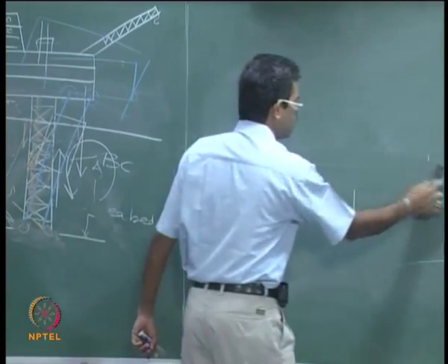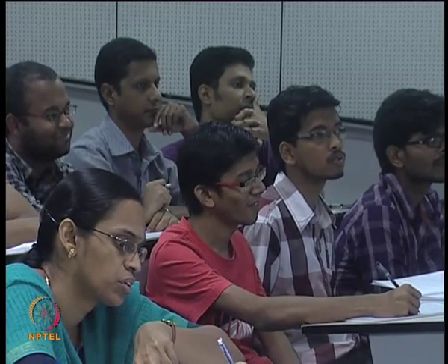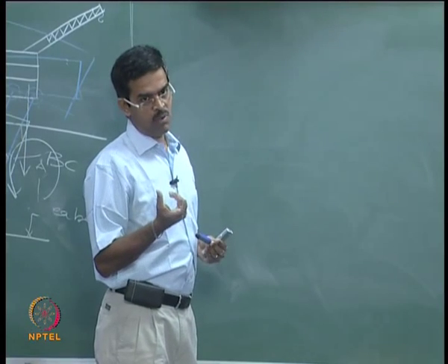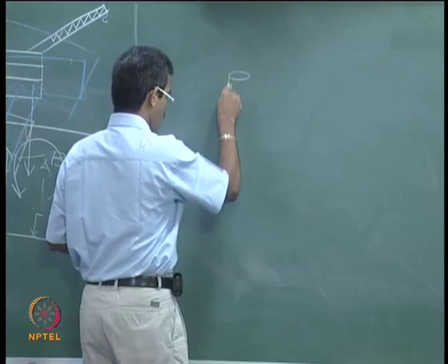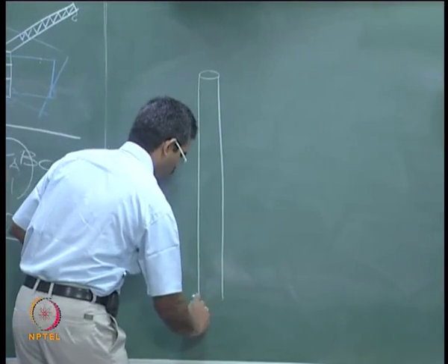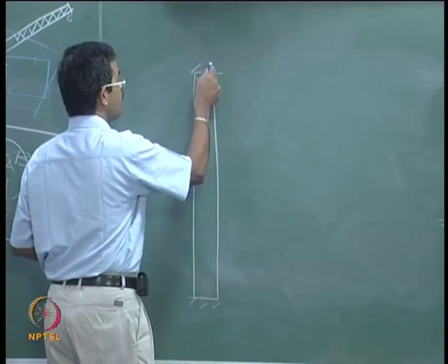Slender. No, we have not talked about any slenderness at all. Slenderness is okay. When you talk about stability, people confuse the slenderness. Slenderness is a proportionality between the cross sectional dimension and the boundary condition of the support. I have the same member very long with a boundary condition. The member may become slender.